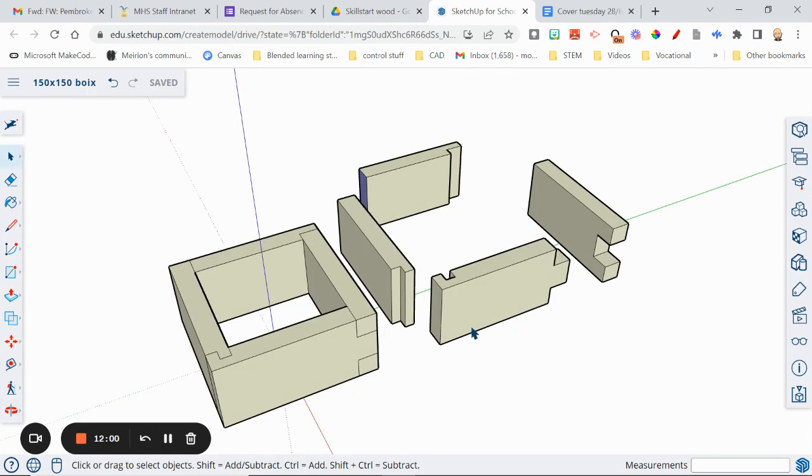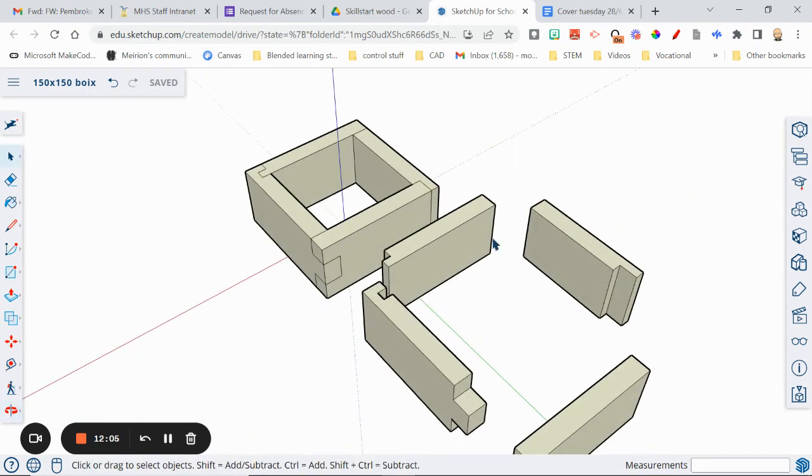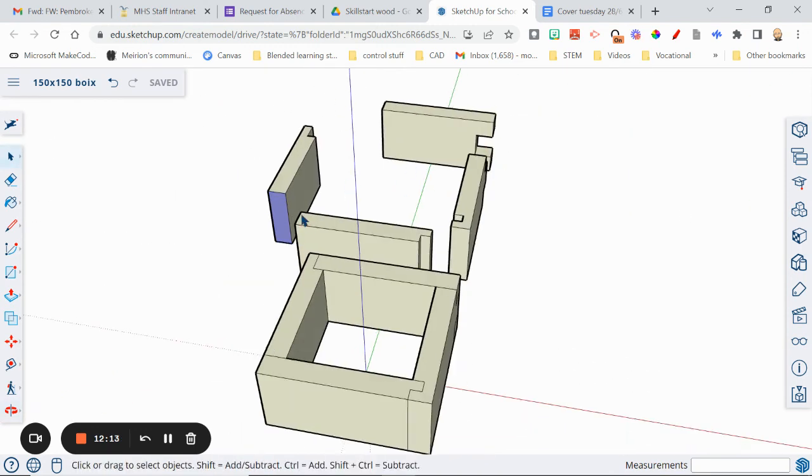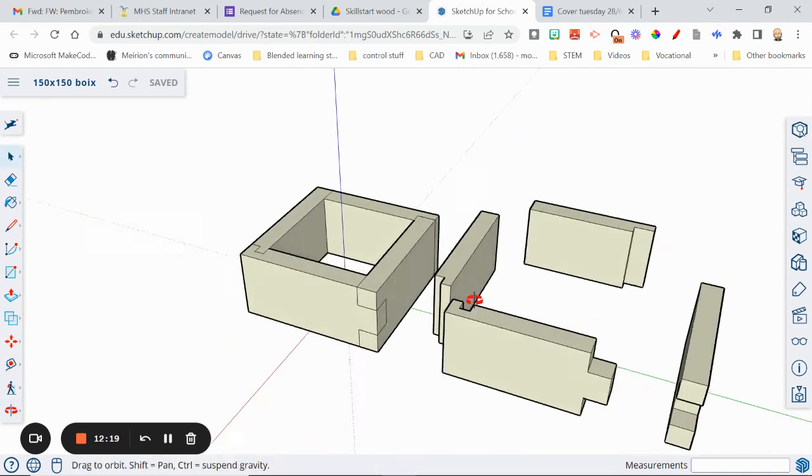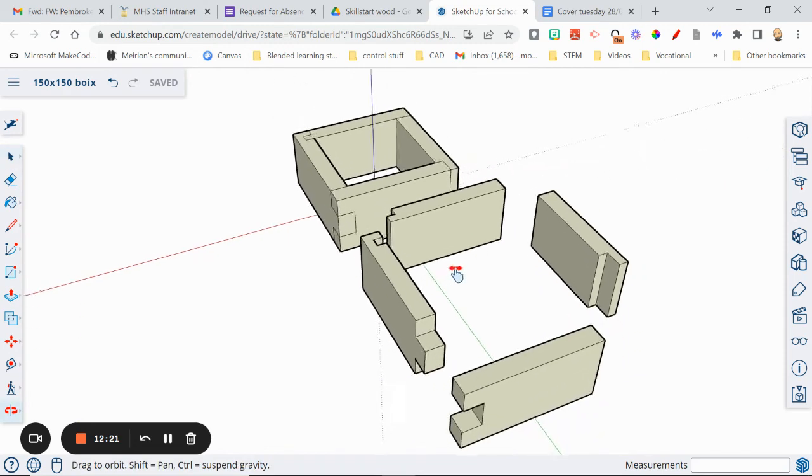If you finish it before one lesson, well, let's think now. I want you moving in and doing the dowels in this section. So half the distance, 2 holes going in, half the depth of the wood, so going in 10 millimeters blind holes, and then 2 holes in the same dimensions that go in 20 millimeters into the end grain of that piece. So that'll definitely take you a lesson to do. So do it nice and accurately.